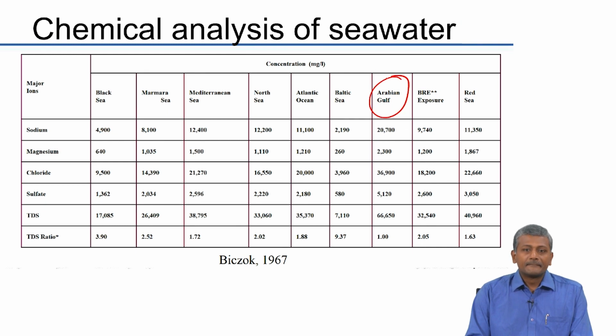Reduce the pH. Sorry? Which can reduce the pH inside the system so that sulfate won't be able to create expansions because of ettringite formation. And the chloride will react with C3A. Okay. So, if you can reduce the pH, how do you reduce the pH? SCMs. Yeah, you can use supplementary cementing materials.